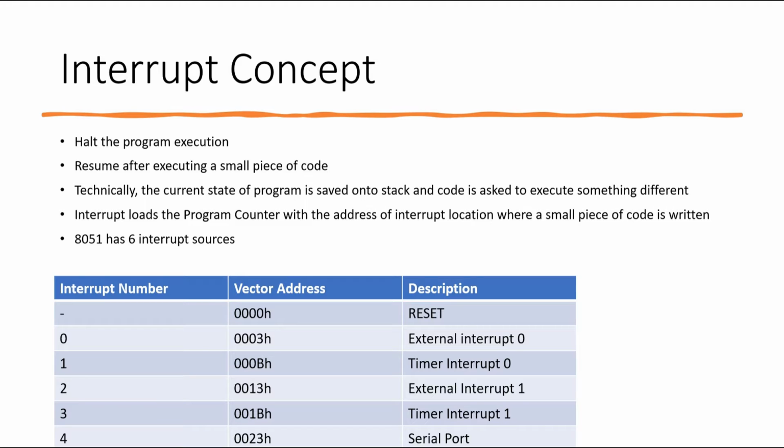Now imagine I'm blinking an LED with a delay of 1 second, and the microcontroller is halted for several microseconds so that it goes to a place, executes something, comes back. My regular delay blinking routine, I will not even notice there is a change. But at the same time, you have achieved something of a multitasking using this interrupt. So this is how it works in microcontrollers.